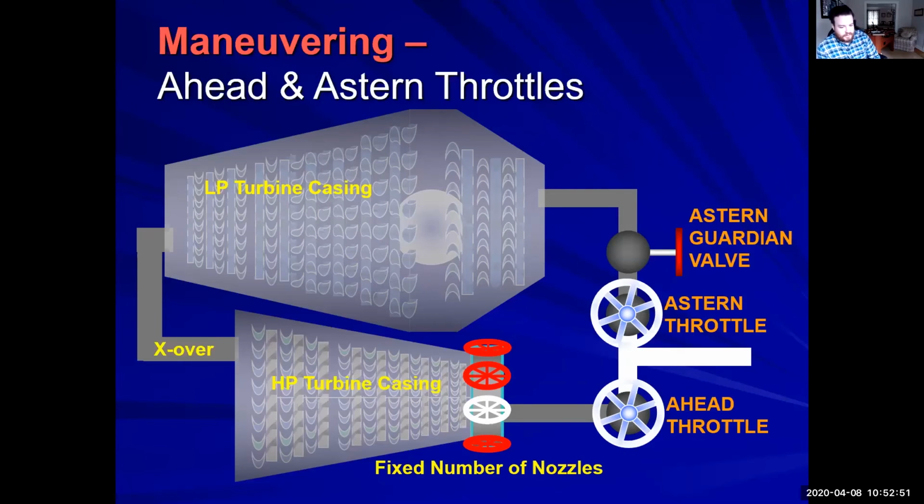Basically, they went from full ahead. They wanted to see our max speed, and how long it would take us to go from max speed to before we started making momentum backwards. So they had all nozzles open. We were running fine. The thought process was that the ship would start to shake. It really didn't shake.